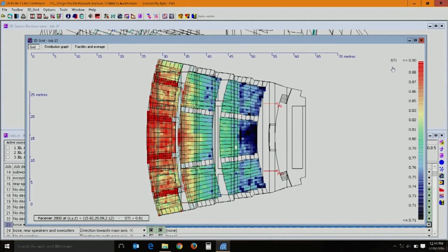Then we have our speech transmission index which we looked at, STI. Here the STI is pretty high and in the front portion somewhere here, the volume is pretty high, the ceiling is quite high. STI is slightly lower, though it is not really low, it is somewhere around 0.7, which is not bad, but still if you have to improve this, either sound reinforcement has to be adjusted, or you have to go with certain reflectors and absorbers, so that the signal to noise ratio can be adjusted.